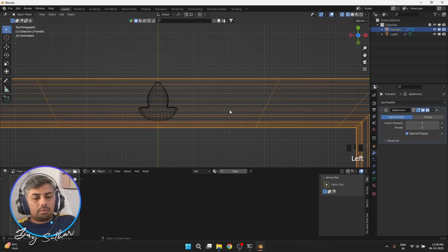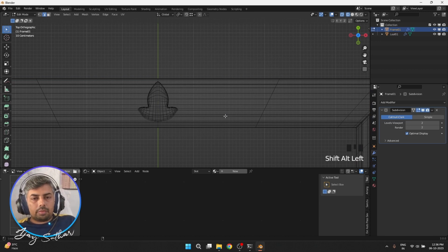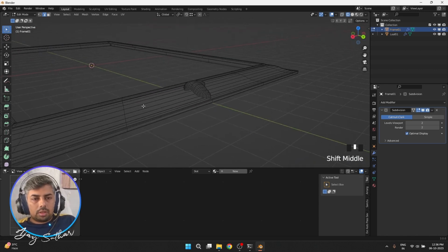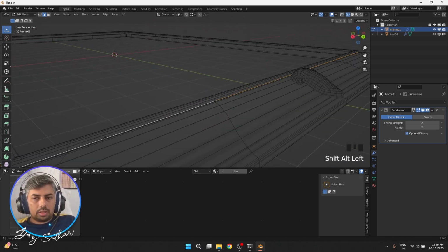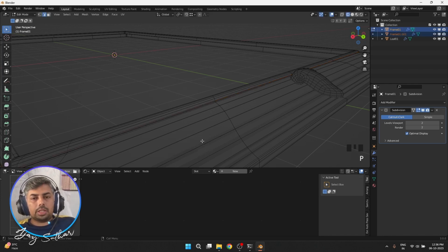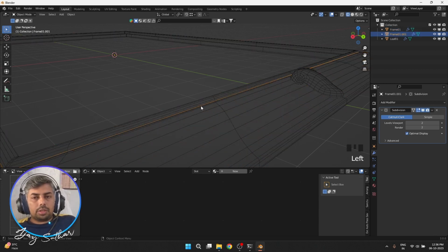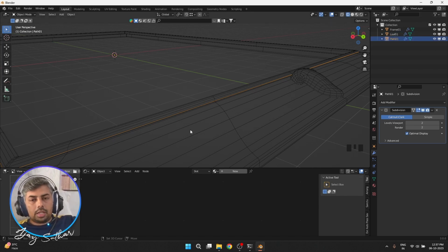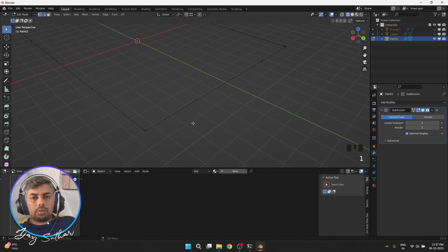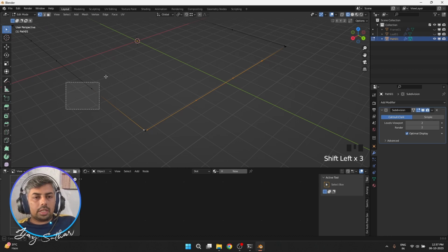Now what I have to do, I have to make these objects travel properly. So I'll take one of the edges from here, one single edge from here, Shift D and enter, and press P to separate selection. Done. Go to object mode, select that separated frame edge, make it path 01. Okay, and Shift H to isolate and work only on the selected object. Go to vertex. I don't want extra vertex in this to make this correct.